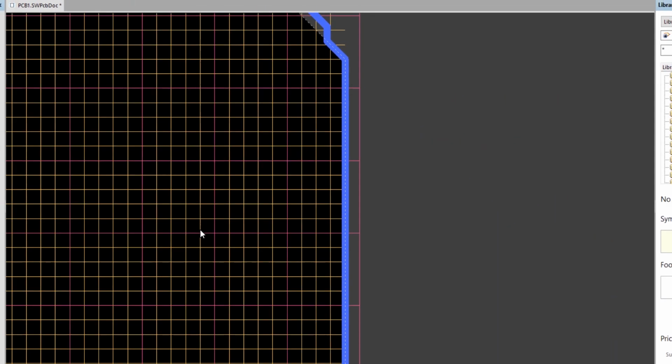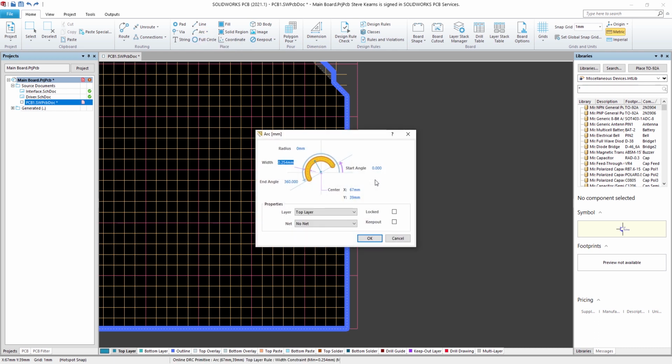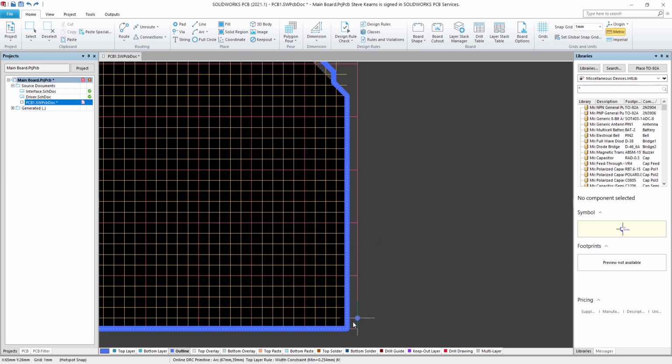Here, after an adjustment on the corner segment, we will add a bulge into the side of the profile, ensuring the final singular shape is continuous. When inside a function, pressing the Tab key opens its properties, which allows for defining its settings before use. Adjusting the upper endpoint of the vertical line allows for the correct portion of it to be removed.